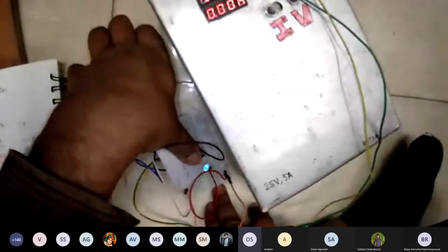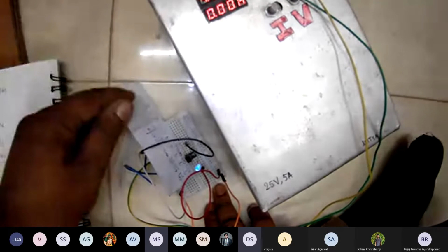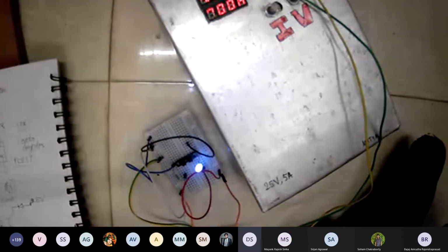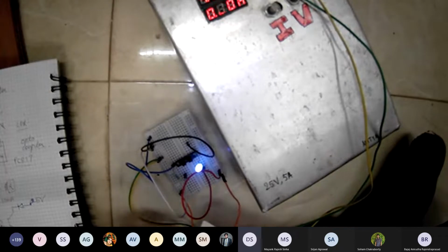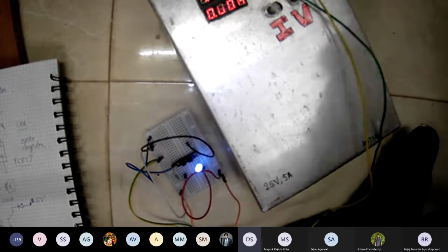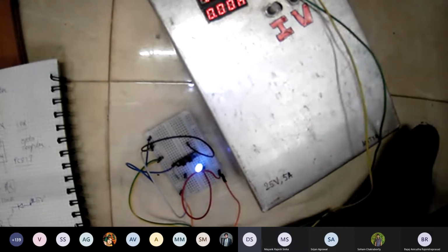Okay. So is the light from the diode infrared? The light from the photodiode is infrared, but the LED which I am using is a blue LED. Okay, sir. So as to minimize whatever crosstalk can happen. I mean, despite being blue, there will be some fraction of energy in the other spectrum as well.